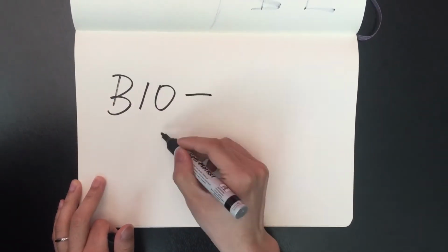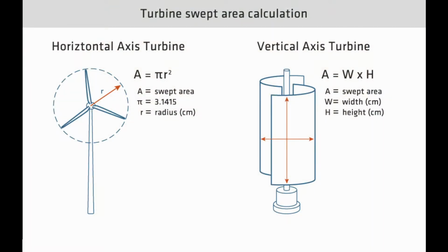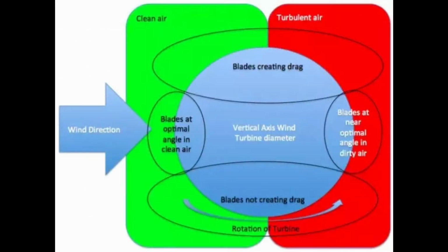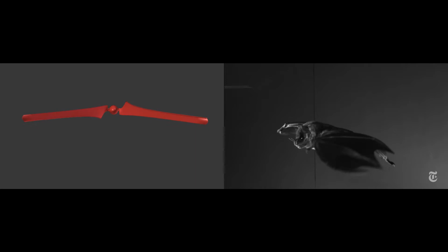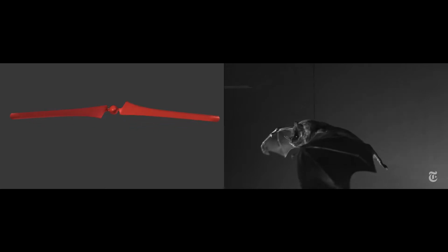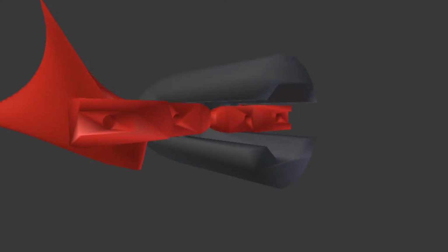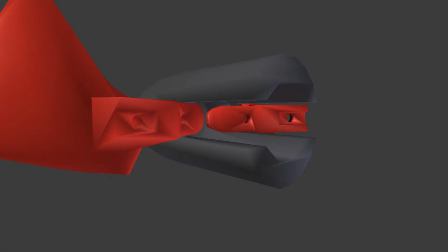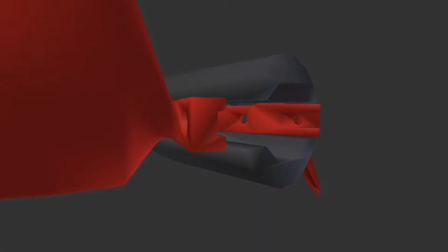Our design objective is to maximize the diameter of the blade, giving maximum swept area for optimum performance. For this reason, we have decided to put a hinge on our turbine blade to fit a 3D printing constraint. Our first hinge design was inspired by a bat wing morphology, which consists of several joints that simulate a flight motion. Due to its complexity in design and time constraint, we have decided to modify the mechanism by retaining only one rotational hinge. This rotational hinge works with clearance fits, which thereby fulfills the design requirement to be printed as one part.